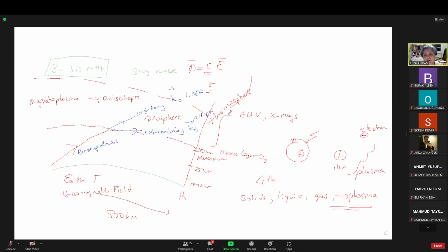When they travel inside the ionosphere, as you see, they have different propagation constants. They have different directions. So these two waves have both the same information. That's the critical part: same info in them. They travel from different paths with different time delays. In communication, this is called a multipath problem.